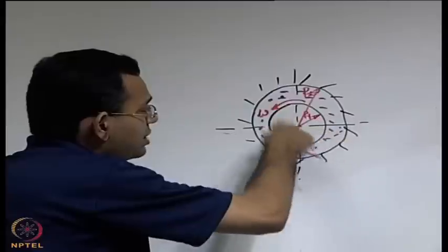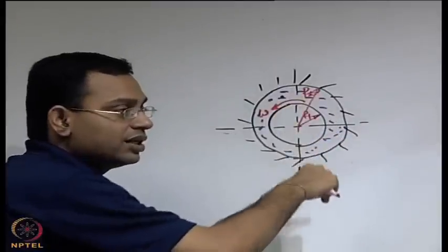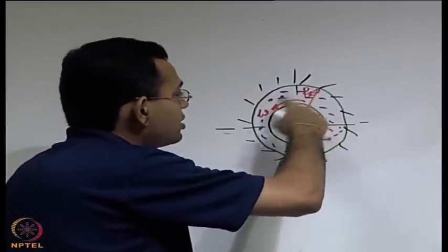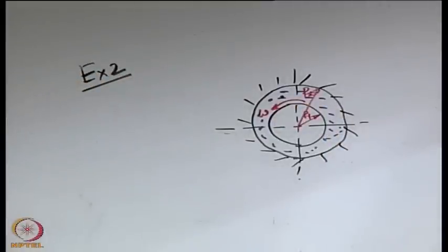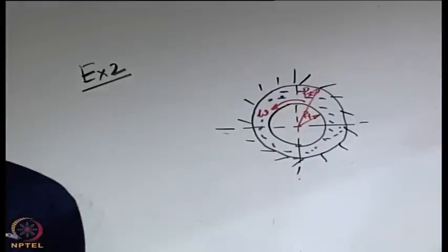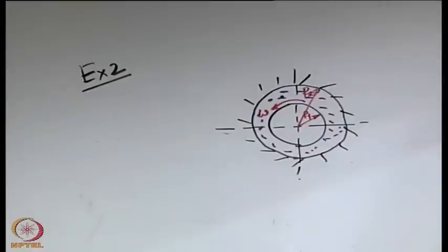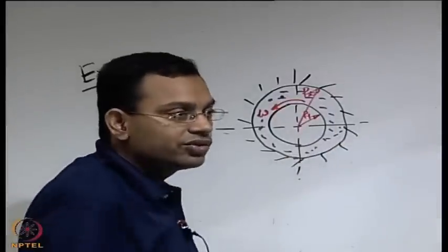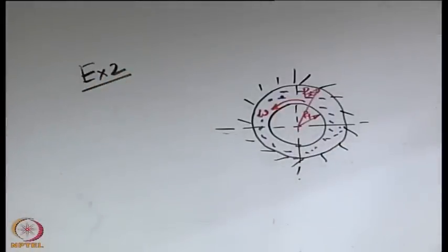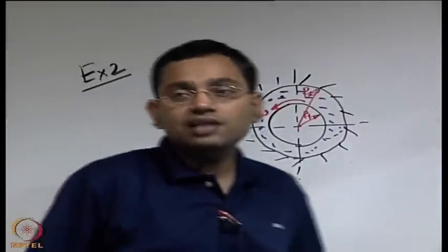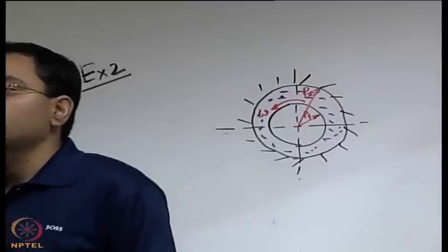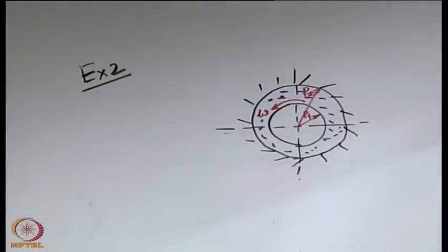Now, because of the presence of the fluid, the cylinder which is rotating is not rotating in an unhindered manner, it is being subjected to some resistance. It has to overcome that resistance and maintain its motion. So, it requires an external power to be imposed, or so to say a torque to be continuously rotating it, overcoming the viscous resistance. And let us say that we are interested to find out what is that torque or maybe power necessary to make it rotate with a uniform angular speed.